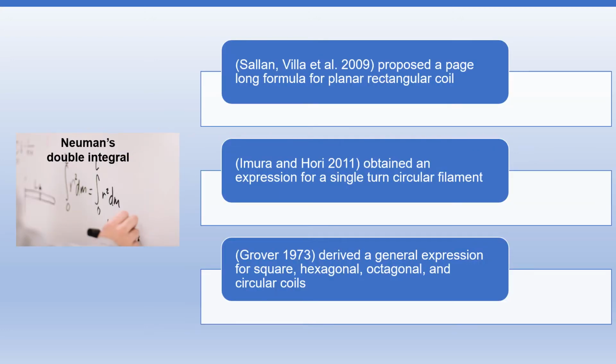Numerous contributions have been made in the literature in relation to the problem of mutual inductance calculation for coaxial circular coils. These contributions have been based on the application of Maxwell's formula, Neumann's formula, and the Biot-Savart law to obtain a general expression, followed by solving analytically or semi-analytically using elliptic integrals, Lagrange polynomials, or Bessel functions, which unfortunately can be quite daunting to deal with. In addition, these derived expressions had limited applications since they have been derived for the case of a symmetrical coupler.